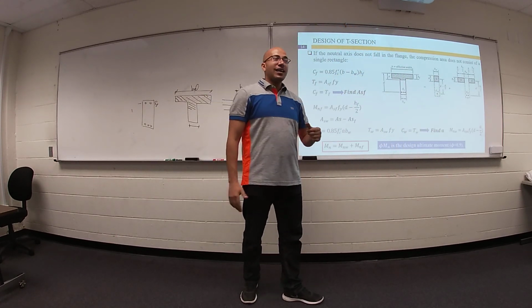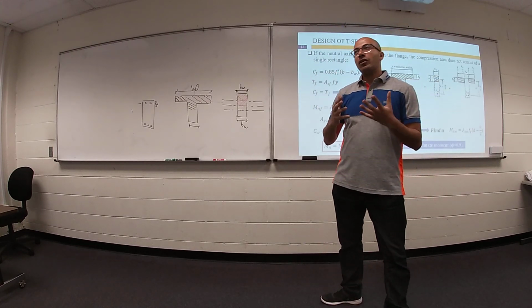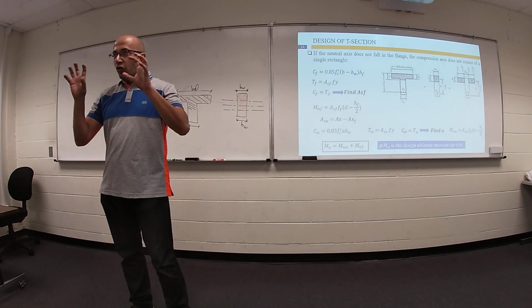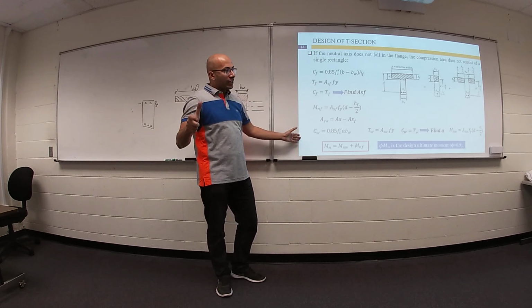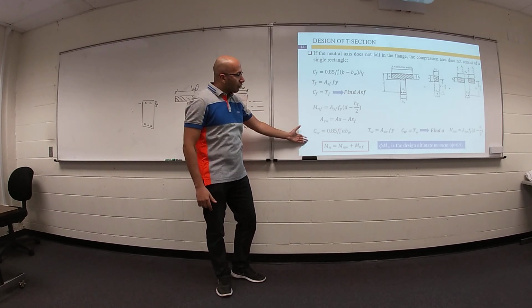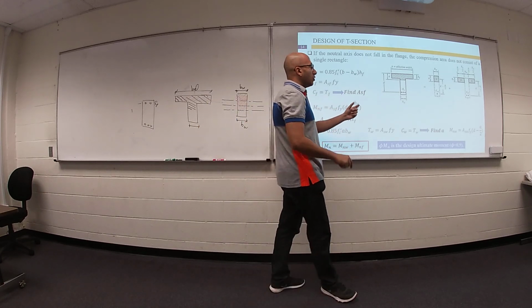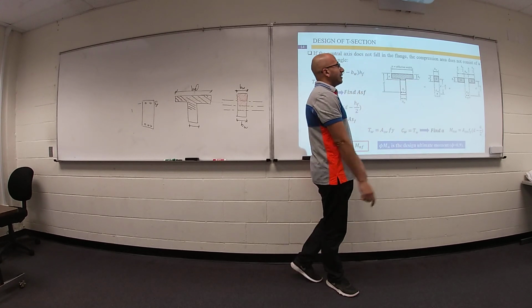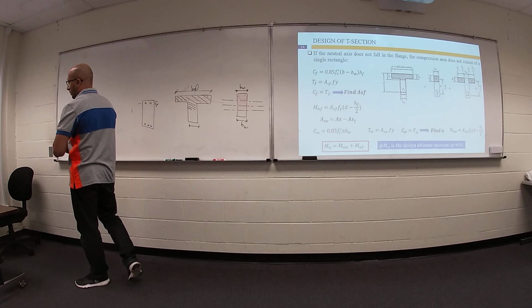And I think if you go to some website like ACI or whatever, you can download design Excel sheets. All of these Excel sheets are based on all of these calculations. If you are good in Excel, you can set up these calculations, this step in Excel. Just put in your area of steel, your depth, your flange width, and the Excel sheet will give you the final design moment.